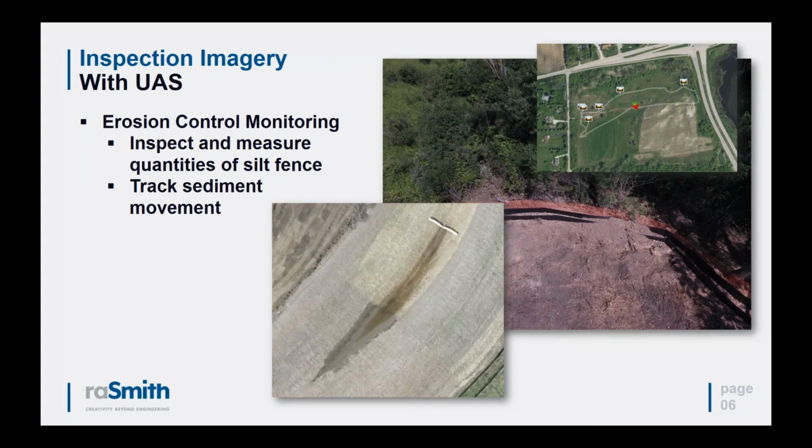And so using a drone, when you go out the first time, and this image inset in the upper right here, you can kind of see a path that more or less represents the path that the drone took on this one particular flight. And each one of those little tiny image tags, if you will, represents a spot along that path where we took a photo.